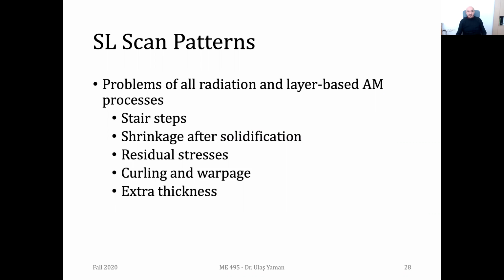So why are the scan patterns important? If you do not have the proper pattern and proper speed, you might have a huge staircase effect. You can see stairs on the side surfaces, and you may have huge shrinkage.